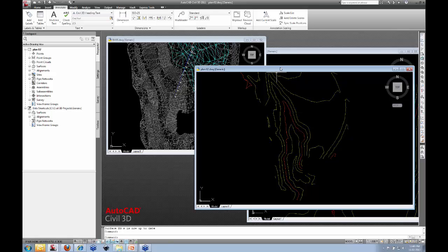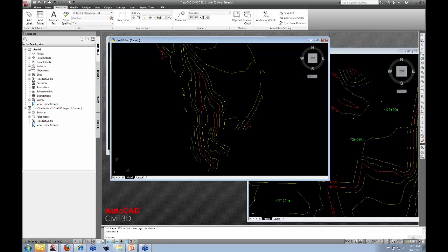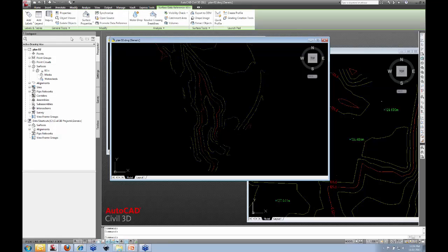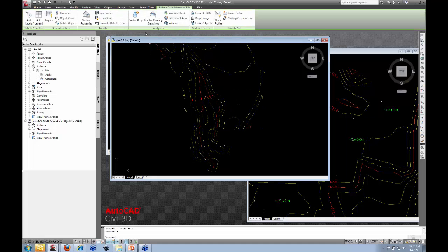The other useful fact, which is a very frequent question we get, is that on this Plan 02 drawing here, you can't do anything to the surface besides change the aesthetics. So I can label it. I can pick the surface, and I can select Add Labels, Contour Multiple. No worries. But when I pick it here, I don't have the options in the previous one for adding triangles or doing anything else.